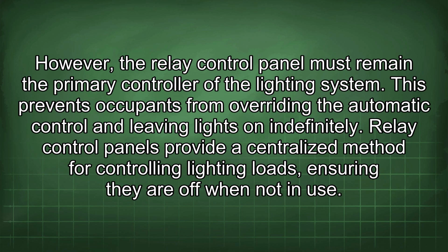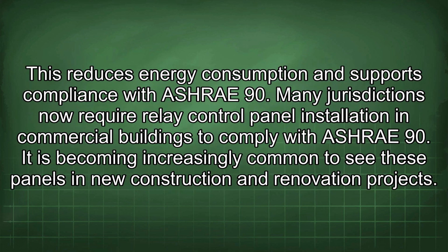Relay control panels provide a centralized method for controlling lighting loads, ensuring they are off when not in use. This reduces energy consumption and supports compliance with ASHRAE 90. Many jurisdictions now require relay control panel installation in commercial buildings to comply with ASHRAE 90. It is becoming increasingly common to see these panels in new construction and renovation projects.